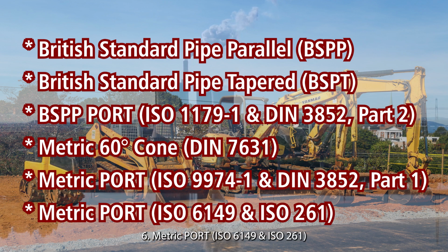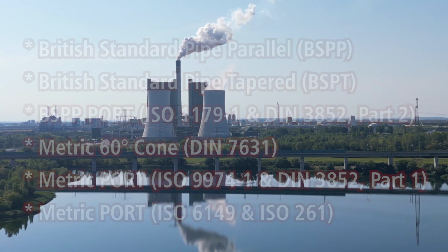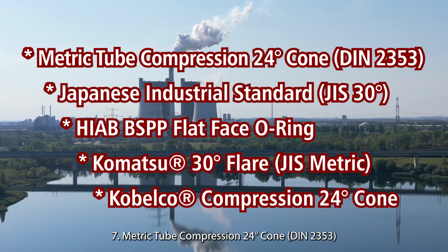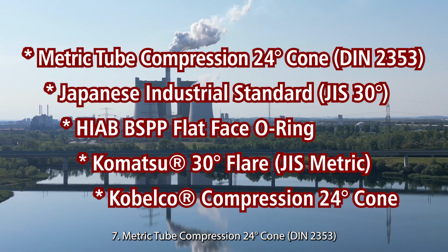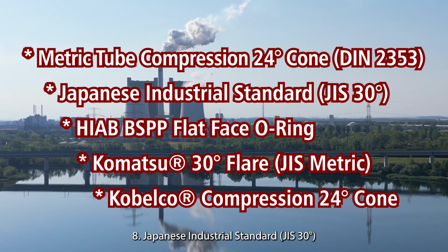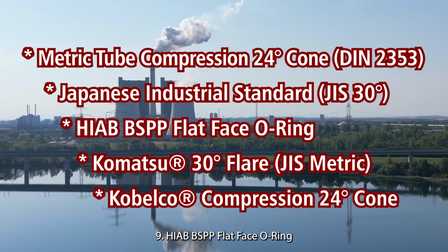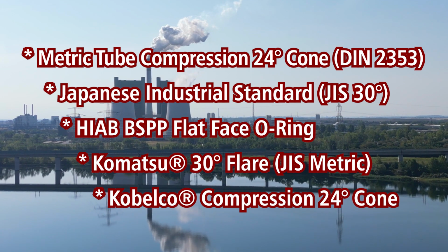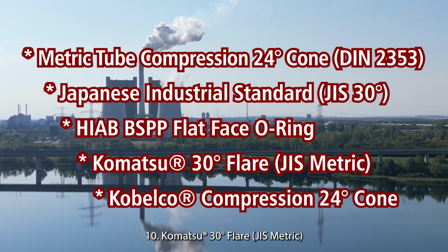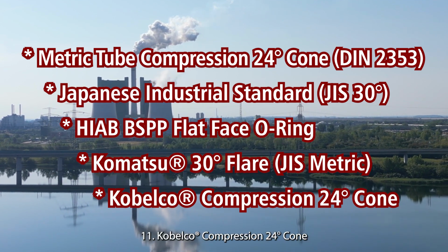6. Metric port, ISO 6149 and ISO 261. 7. Metric tube compression 24 degrees cone, DIN 2353. 8. Japanese Industrial Standard, JIS 30 degrees. 9. HIAB BSPP Flat Face O-Ring. 10. Komatsu 30 degrees flare, JIS metric. 11. Kobelco compression 24 degrees cone.